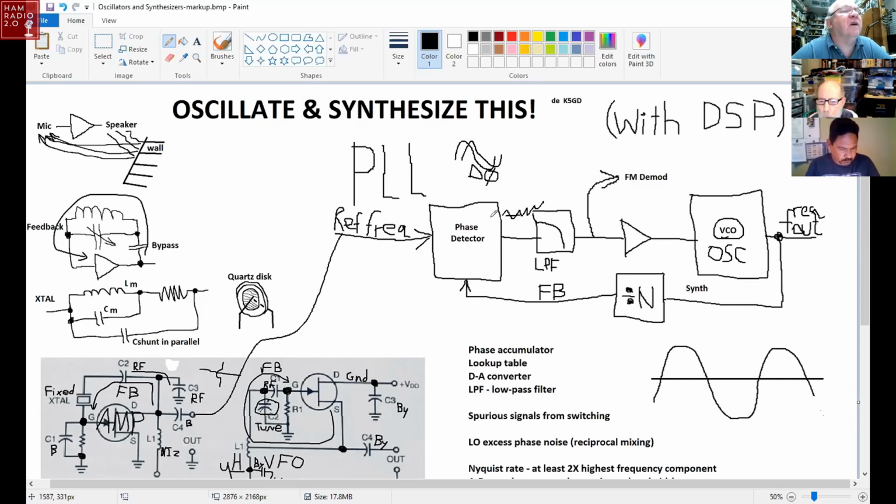Here there's a delta in phase, which is what the phase detector provides for you. Out of the phase detector, you get a DC level with some noise, AC high frequency stuff on it. So you have to go through a low pass filter to get just a low frequency signal or DC. And you can use the phase lock loop as an FM detector. You pick off what comes out of the low pass filter.